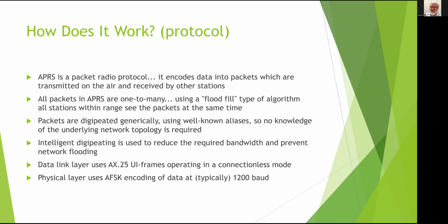It uses these UI frames in connectionless mode, and the physical layer uses AFSK encoding of data, typically at 1200 baud. AFSK is audio frequency shift keying. So there's two tones that are mixed together, and it encodes the bits by changing those tones. And so typically what you'll hear on the radio is something that sounds like, and that's the actual data that's being transmitted.